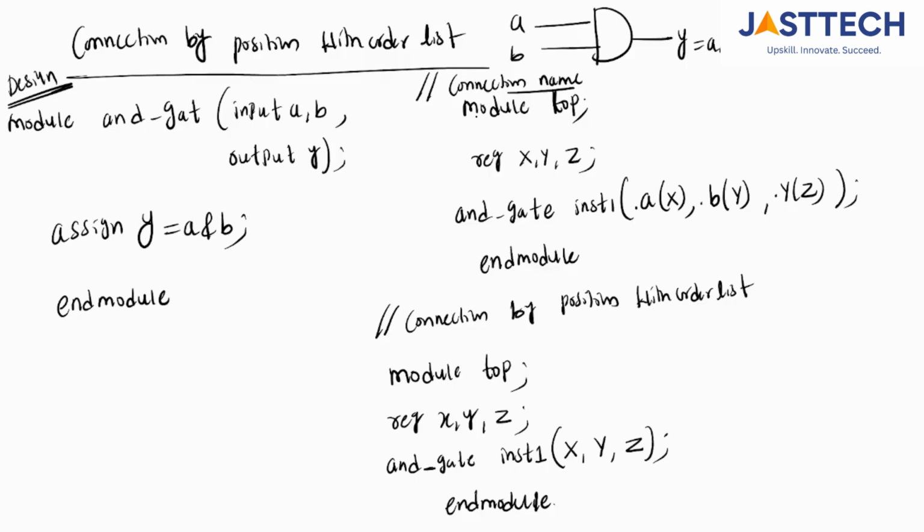Similarly, the parallel adder. We are designing the parallel adder, that means ripple carry adder, BCD adder, or carry look-ahead adder. We are implementing those parallel adders by using full adder circuits. There we are using four full adder circuits. Every time we can't write the code for each full adder, as the programming length becomes complex.